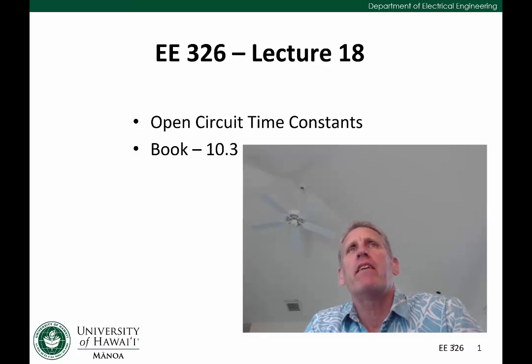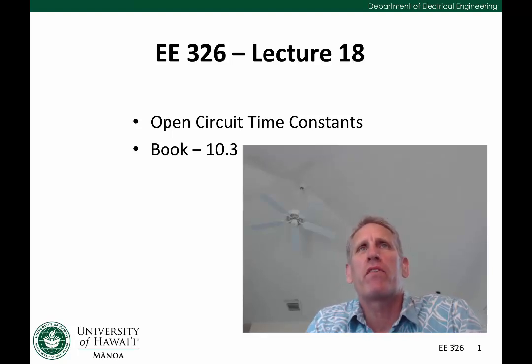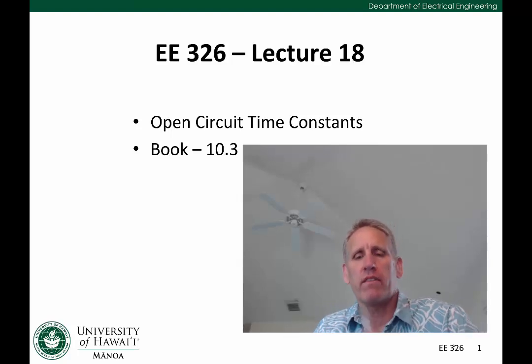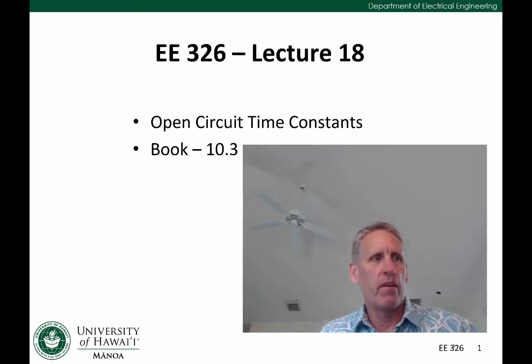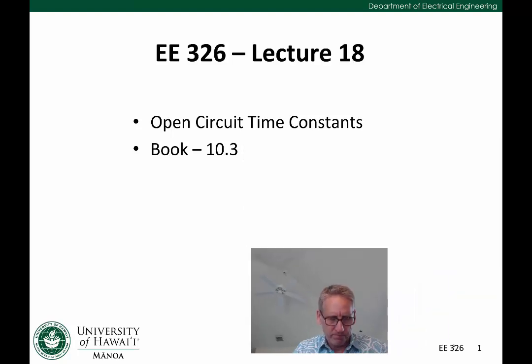Today I'm going to be discussing a technique to evaluate the frequency response of circuits when we're unsure about how the circuit's going to behave. That is, we're not sure where the dominant pole is. The technique we're going to be talking about is called the open circuit time constant technique. In your book, this is section 10.3. All right, let's get started.